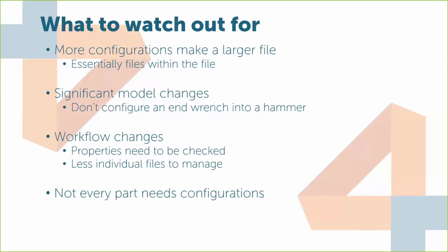Another thing to think about, kind of categorized under workflow changes. I'll use that example of 15 discrete part files now into one part file with 15 discrete configurations. You need to think a little bit about, well, we've got fewer files to manage. How do those integrate into our PDM system if we're using one? How are we going to leverage the configurations in different parts, different assemblies, different drawings?